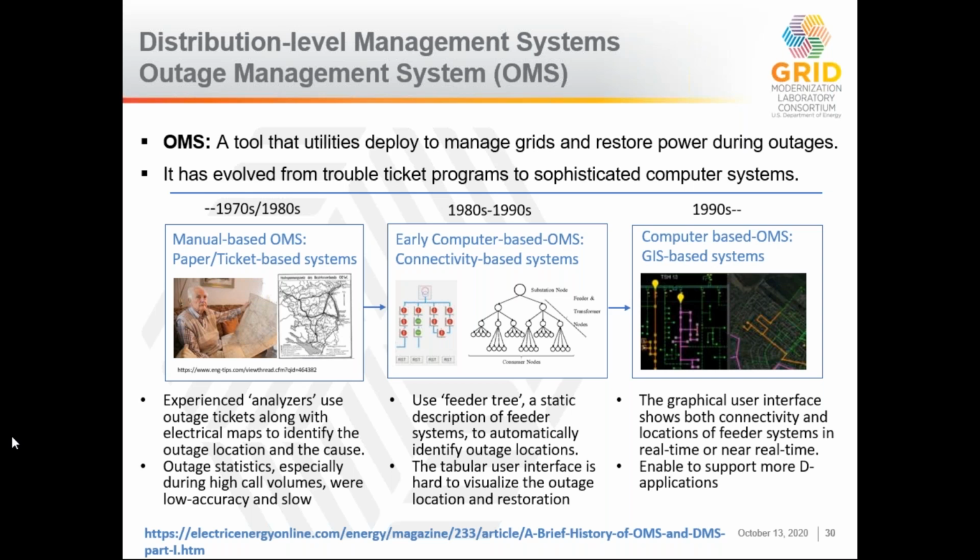There's a few different origins for where the data comes from on that. There are distribution planning models, but both of them are based generally in the geographical information system, where they essentially import a version of the topology and geography of the distribution system. So when they're sending someone out to fix an outage or investigate a problem, they know where they're going, they know the topology of it, and they know what it looks like. It also helps them locate these things a lot quicker. And there is more connection now to measured data systems, including distribution SCADA also.